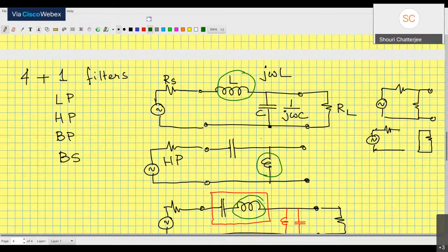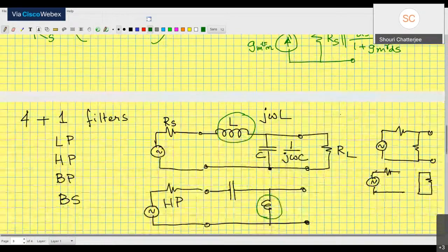That is the better approach of designing these active filters. So these are the two ways in which active filters are made: replace the inductor with a gyrator based circuit which simulates the inductor, or emulate the signal flow graph of the circuit using op amps and RC. That's why you want to go to active circuits and not have passive RLC filters.